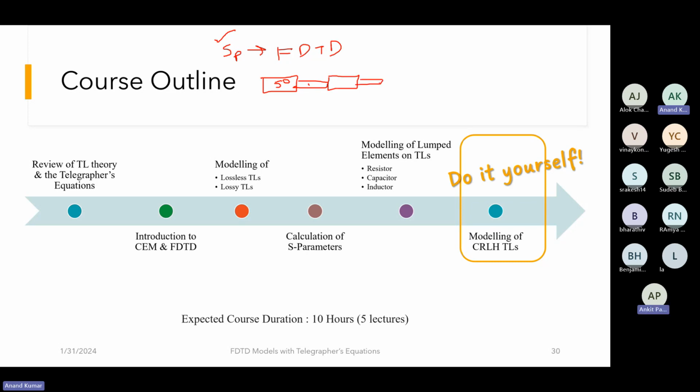So this is how it will look. In FDTD we know how to simulate this because we have done that in the class. Now what you can do is, you know the length, you know the impedance, so you can calculate the ABCD matrix of this particular section, which is written in terms of something like tan beta L, sin beta L, cos beta L. It's there in the textbooks and in Pozar. So it will be a 2 cross 2 matrix for each section, and for each section we write down the ABCD parameters.